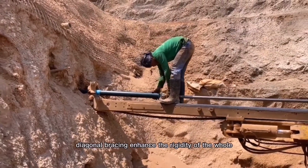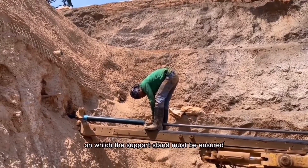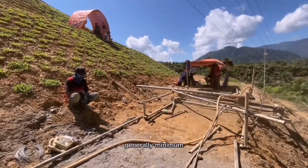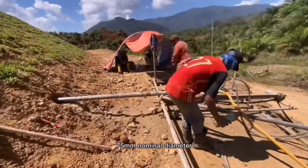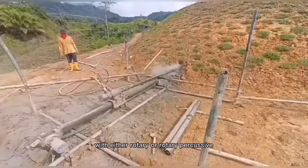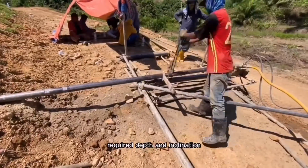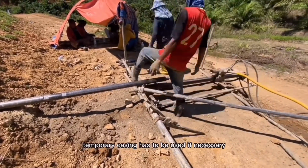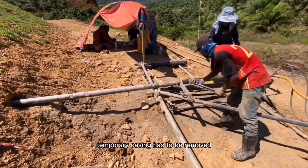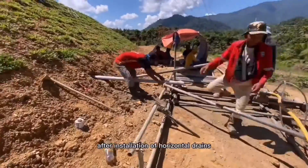Having extra diagonal bracing enhances the rigidity of the whole frame, and the firmness of the ground on which the support stand sits must be ensured. Generally, a minimum 75mm nominal diameter borehole is drilled at the required location with either a rotary or rotary percussive drilling machine to the required depth and inclination. Temporary casing is to be used if necessary to stabilize the boreholes. Temporary casing has to be removed after the installation of horizontal drains.